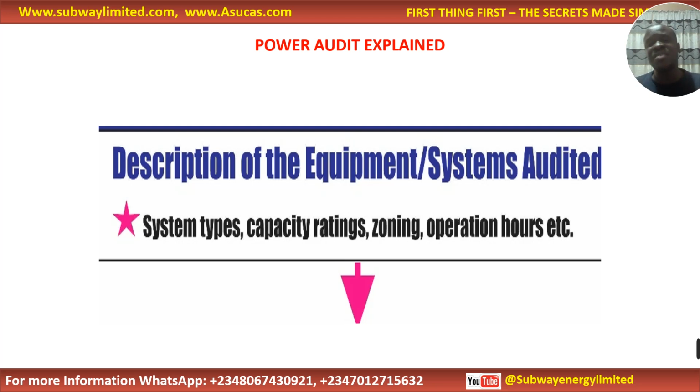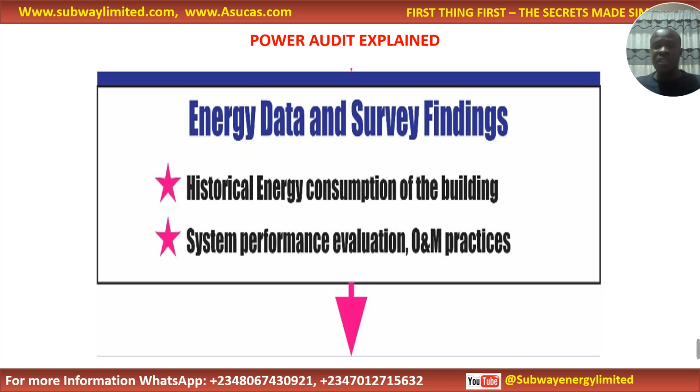You need to study the electrical load. For capacity rating, you need to take into consideration what the power consumption of each electrical load is. That is capacity rating, zoning, and operation hours, that is, how many hours each electrical load will be operated. You need to take all these things into consideration during a power audit. We are talking about a professional way.